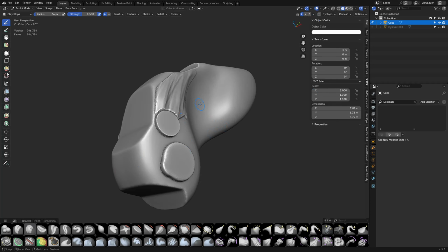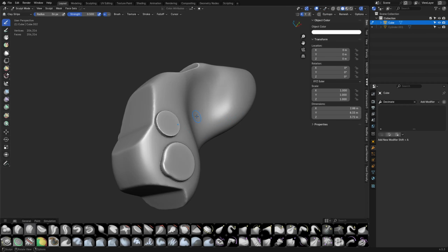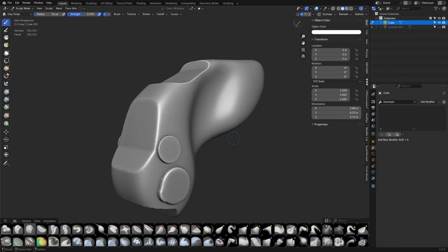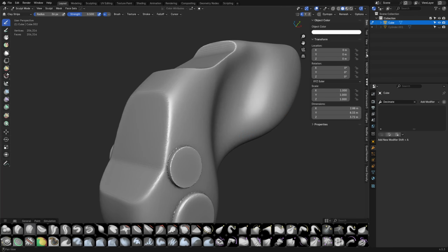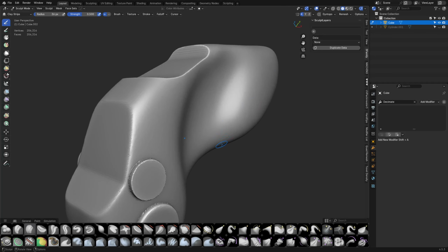But if it's a multires, for example, it's going to have a really hard time with something like that. If you're using the layers tool or the layers add-on, right? Blender does have a sculpt layers add-on, and right here, usually we use this. Well, you can use it on any mesh. But you're going to turn this kind of thing on when you're certain you want to start adding detail, more than likely, because you can't change the vertex counts.